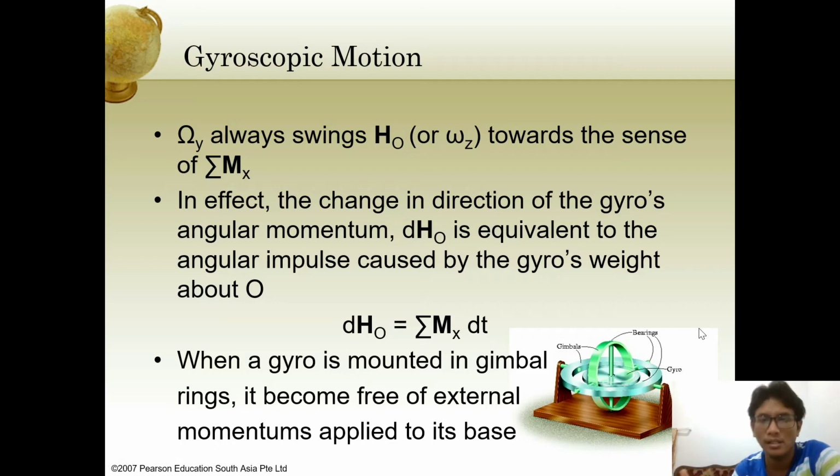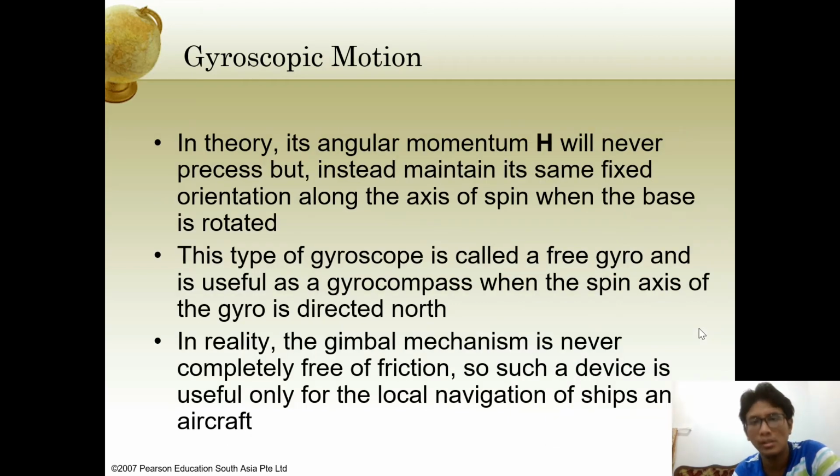But in other applications, which are not the free gyro, we can apply it in so many situations. For example, in your car wheels, in your motorcycle wheels, in a gearing system, there will be unwanted gyroscopic effect. For example, the precession. We don't want precession in our gearing system. It will disturb the system. It can cause damage or misalignment. So we don't want gyroscopic effect, and we need to learn about gyroscopes.